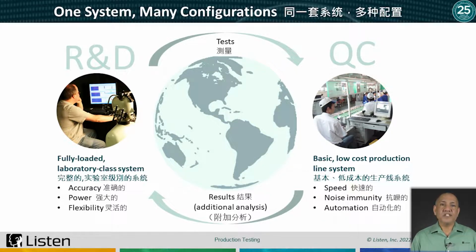Audio testing needs are different between the two environments. In the development phase, you are interested in fully characterizing your product. Typically, you have time to carry out tests, so you can use longer test stimuli. You might test using different stimuli, like frequency step or continuous sine sweeps, amplitude sweeps, multitone, pink noise, speech, or even music.